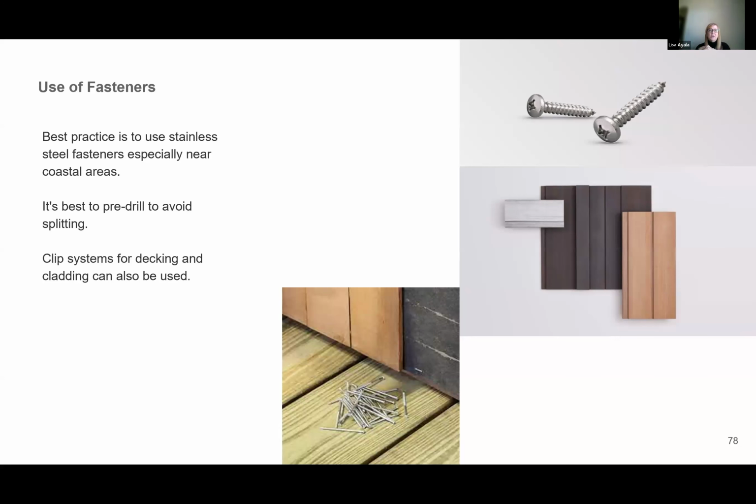On the harder woods, it is better to pre-drill, like the ash and the radiata. And also, there's a lot of clip systems out there nowadays, and we find that most of those work as well.